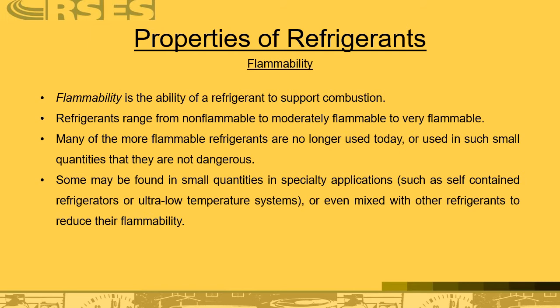Here's a rather sore subject with refrigerants. The flammability properties. Flammability is the ability of a refrigerant to support combustion. Refrigerants range from non-flammable to moderately flammable to very flammable. Many of the more flammable refrigerants are no longer used today, or used in such small quantities that they are not dangerous. Some may be found in small quantities in special applications such as self-contained refrigerators or ultra-low temperature systems, or even mixed with other refrigerants to reduce their flammability.